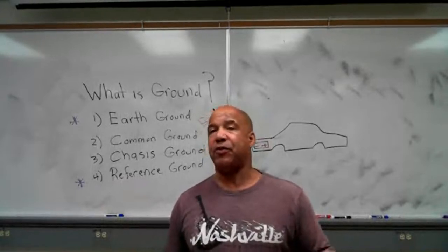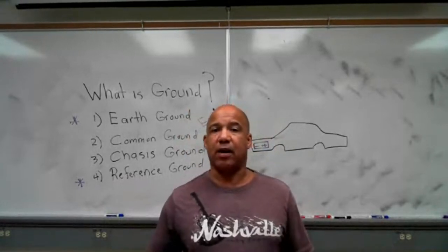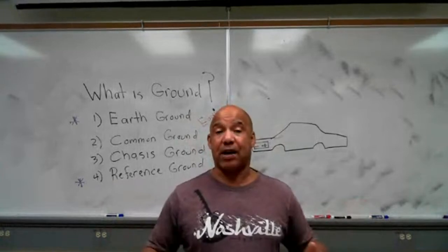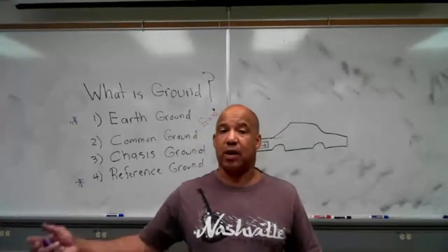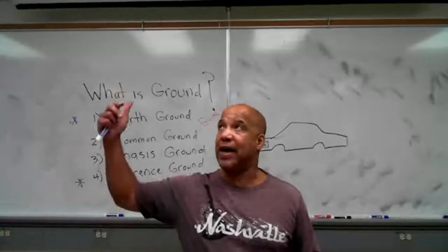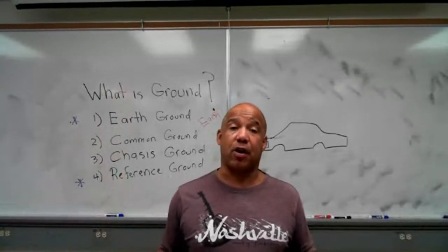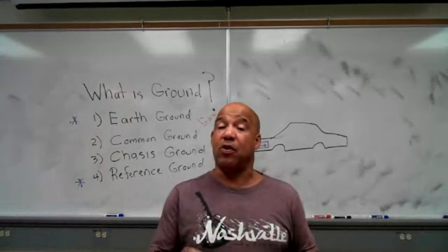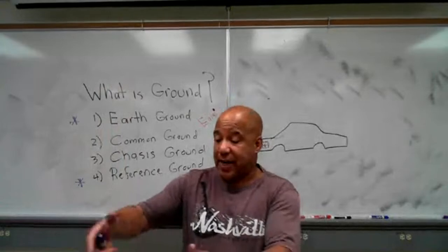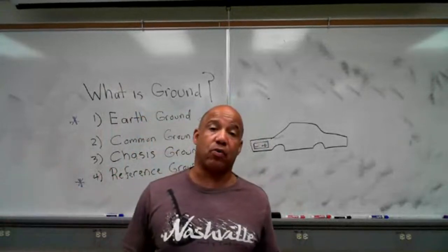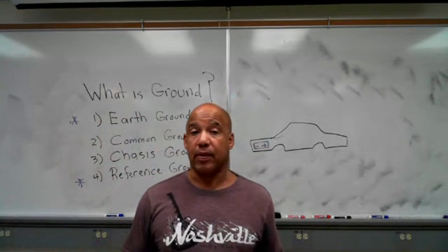Now, I take that back. If you're sitting with your engine off and listening to the radio, well, at that point, you're still using the battery. So it's to start your car and to power stuff when you have your engine off, like a dome light or a radio, right? Other than that, it's just to start your car. I'm not telling you to do this, but if you wanted to, you can start your car and carefully disconnect your battery, take it out and set it on the ground. Your car's still going to run. Now, when you turn it off, it won't start, but it'll run.